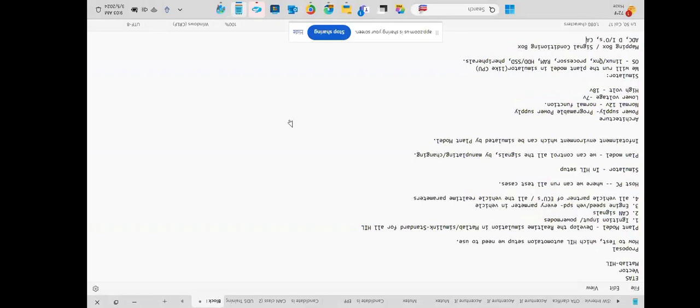And on the CAN, LIN, and Ethernet, all the protocols. The signal conditioning box, the mapping box, has all the interfaces. For example, if the ECU wants an ADC input, this box will give it. If it requires digital input or output, the mapping box will give that.